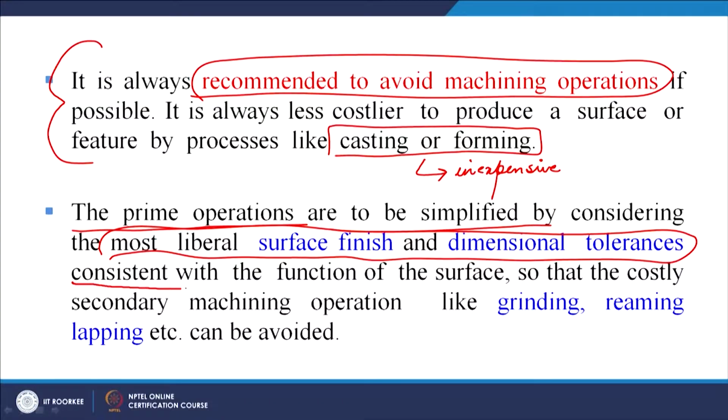Maybe a single machining operation may give us the kind of surface finish and dimensional tolerance that we plan to include in our product design. So we must not overemphasize the importance of surface finish. Why? Because we must be consistent with the function of the surface. If the surface does not require a very high surface finish, we must not overemphasize that this is the basic level of surface finish required.